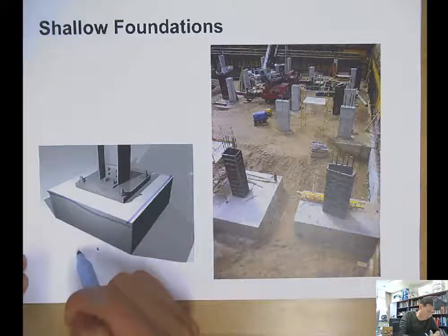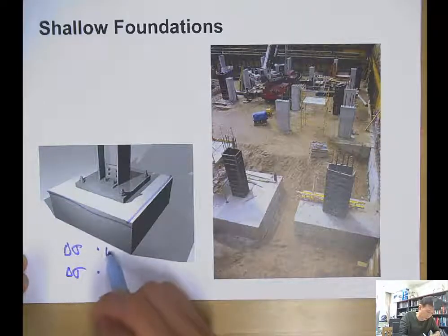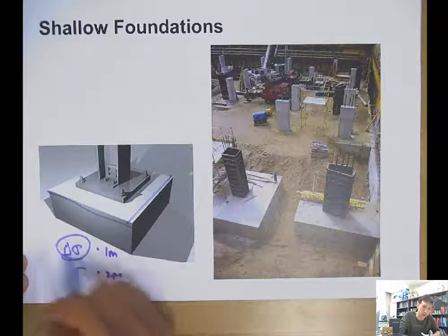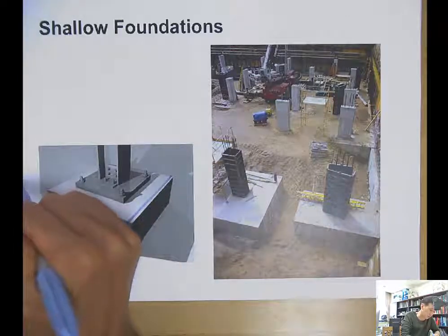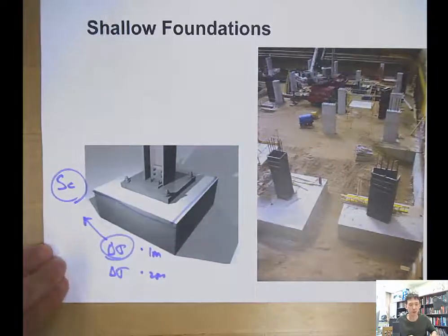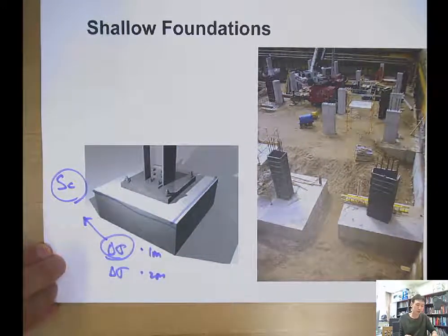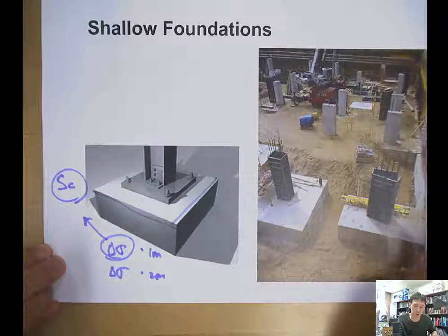If we know the total stress increment at each depth, we can compute the ultimate settlement. So that starts another consolidation settlement estimation procedure.